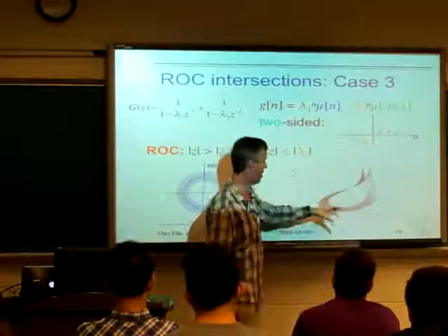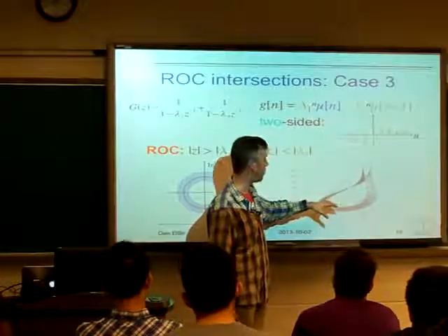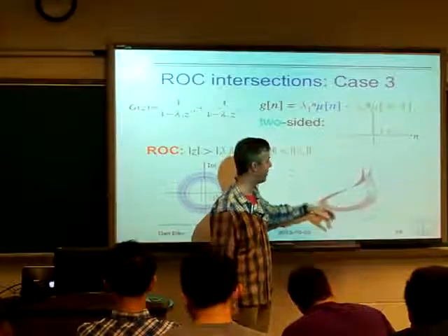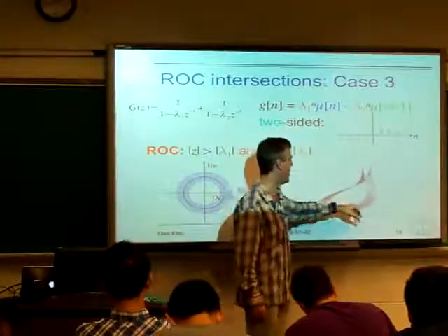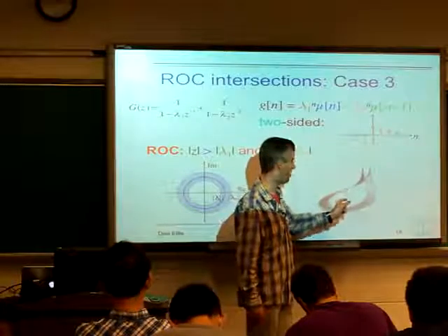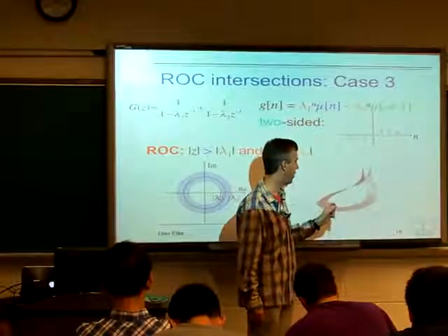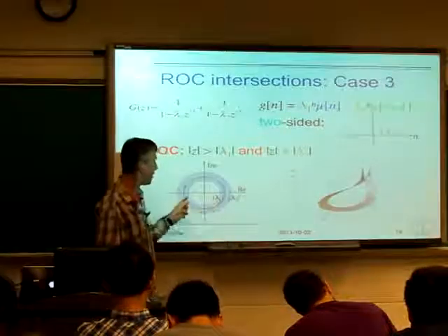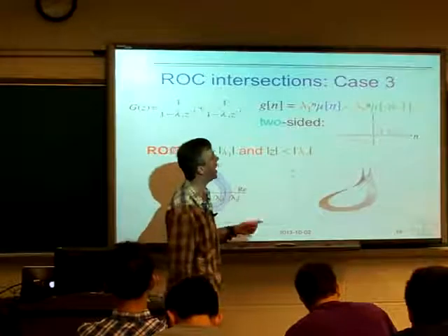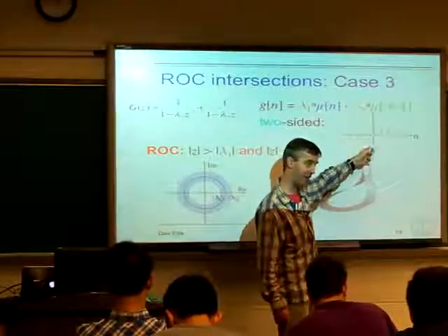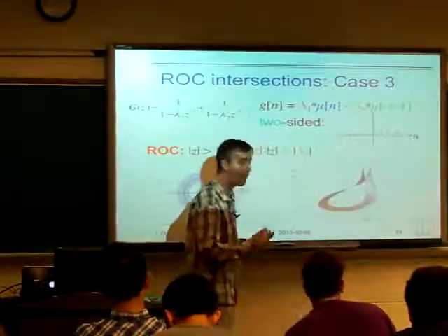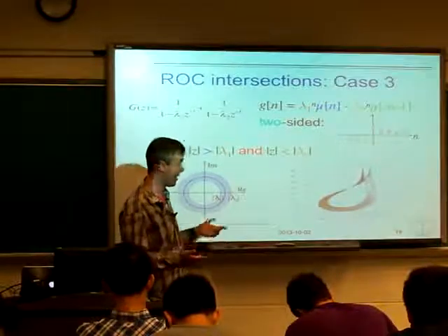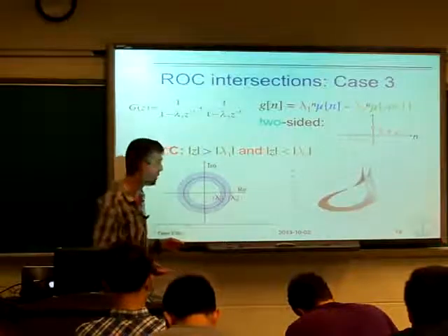And so again, we've plotted the entire Z transform magnitude here for all values of Z, but where it's not visible, it's because it was divergent. But there's just a set of values of Z over this fixed range of magnitudes where the sum converges. Now we notice that the unit circle is in the region of convergence, and this is a signal with bounded magnitude, something we can calculate its Fourier transform, and we can evaluate G of Z for Z equal to j omega.